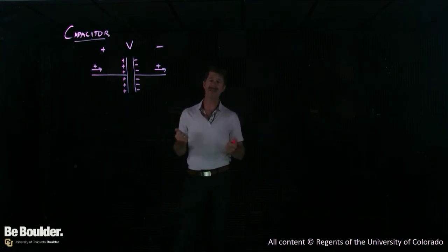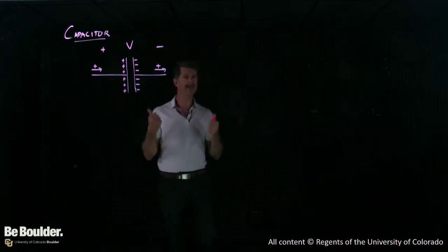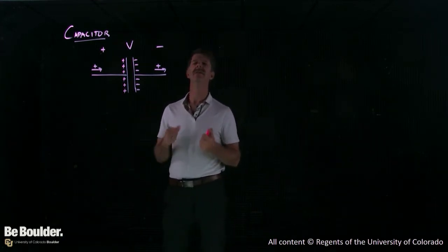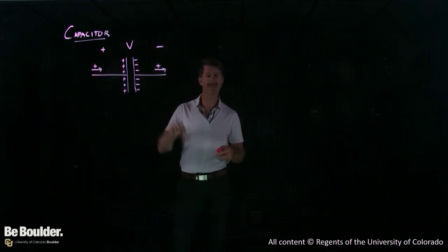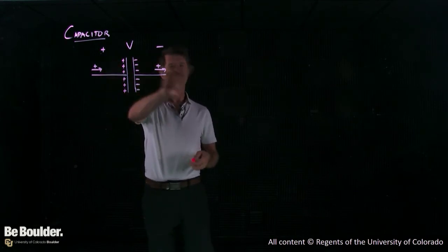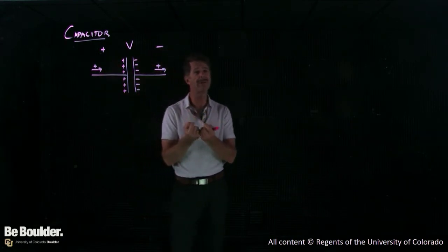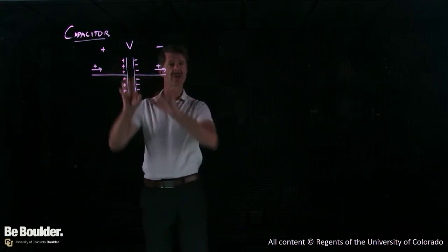So what this means then, in terms of using the device, is if we put a static DC, constant voltage across here, and maybe we turn that power supply on, we might see a little blip of charge come out, a small amount of current for a small amount of time as these plates charge up.